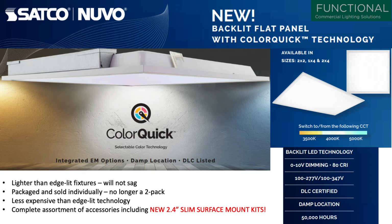Why? Because most of the ceilings are suspended and these fit right in or lay in to the suspended ceiling. In the model that you see in front of us, this is a flat panel that features color quick with 3 different color temperatures that can be adjusted by moving the switch. It has 2 voltage packages, 100 through 277 and 100 through 347 for those applications that may be in Canada. It's DLC certified, which makes it available for utility rebates and is 50,000 hours.